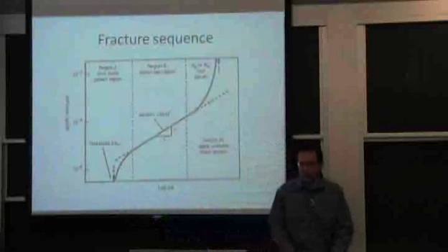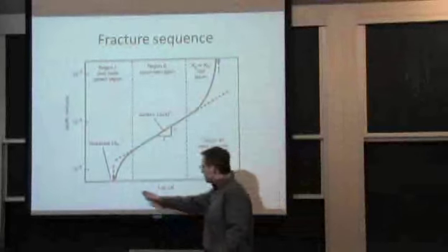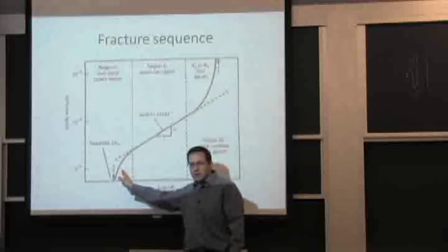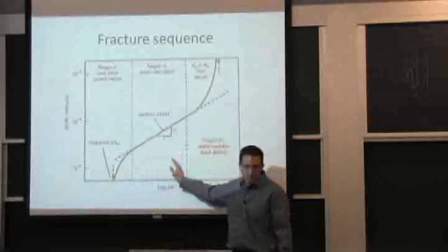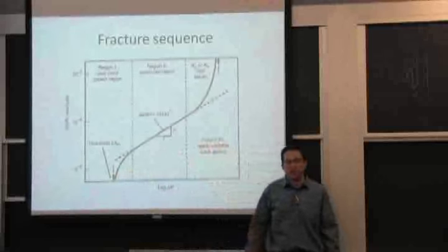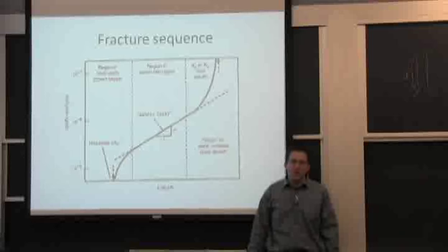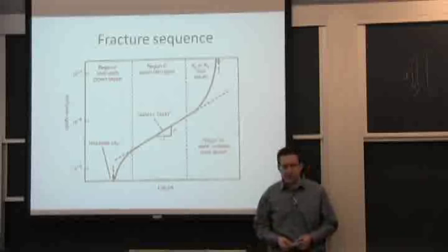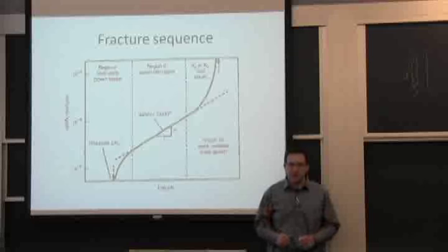It really depends if it's aluminum or steel. So you can be in a condition where you can use all the equations we talked about, but not all the way to the fracture toughness. You may have to stop before that, but you'll normally have to stop when cracks are already pretty big. So it's not necessarily a big problem in terms of a fatigue life assessment.